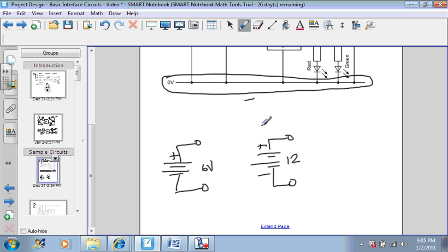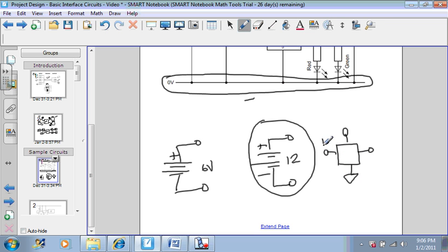Normally what happens is that you have a 12-volt power supply, and then you use something which we will talk about later called a voltage regulator that will allow you to put in 12 volts and output 5 volts, like a voltage converter. And you can also use something else that we talked about before called a voltage divider, where you put in 12 volts and you select the correct resistors to output the 5 volts. In this example, I'm sorry, it's 6 volts, but you get my idea.